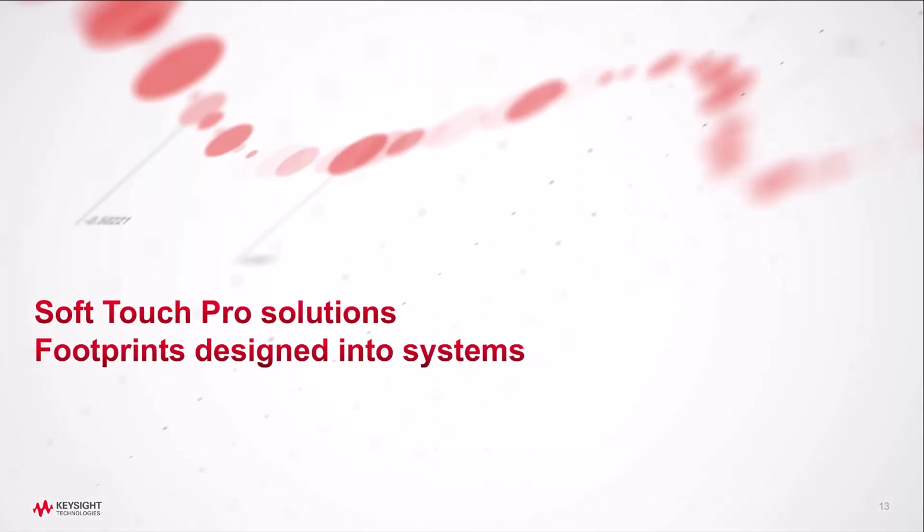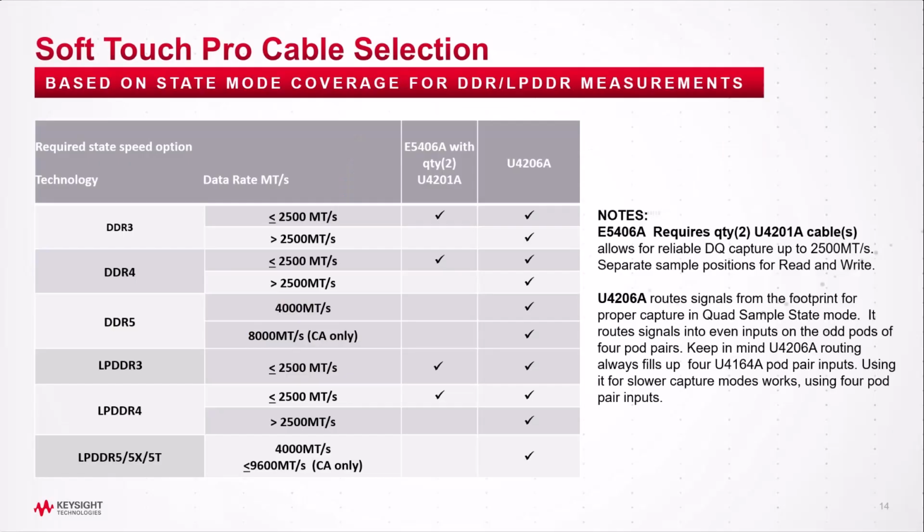Now let's cover Soft-Touch Pro solutions, where you design a footprint into the system. There are 2 cables to consider for capturing DDR3, 4, and 5 or LPDDR3, 4, and 5 traffic. The E4506A Pro with quantity 2 U4201A cables can be configured to operate in dual sample mode and capture the DQ for the memory all the way up to 2500 megatransfers per second.